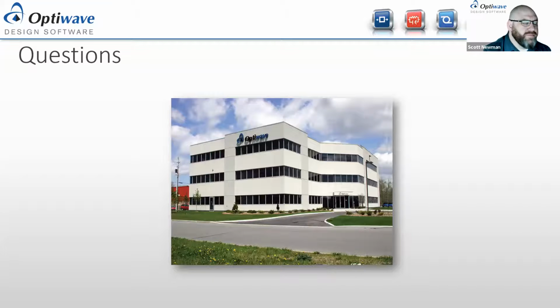They can be in the ballpark, but if you're looking to nail it down, I would recommend running 3D simulations. So you would want to define the thickness and run a 3D FDTD simulation.